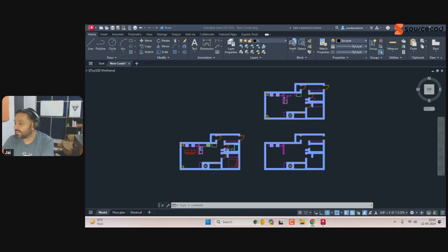Okay, so line type and its global scale factor. So that's the LTSCALE command for that. You can use LTSCALE just to set its global scale. Okay, that was, by the way, an answer to Anand's question, Anand Raj.